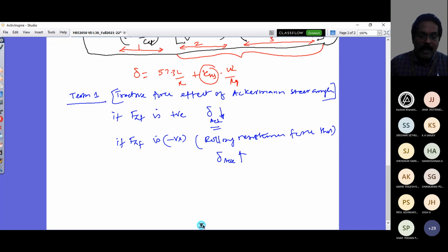So you can also look at when the front wheel spins on snow or ice. We know very icy surfaces cause front wheel spin. So with a front wheel drive vehicle, when you are starting the vehicle, rather than the vehicle translating, the wheels are spinning. That is called 100% slip. That's why it is spinning. So what do we mean by that? The tractive force is still produced, but C alpha F goes to 0.